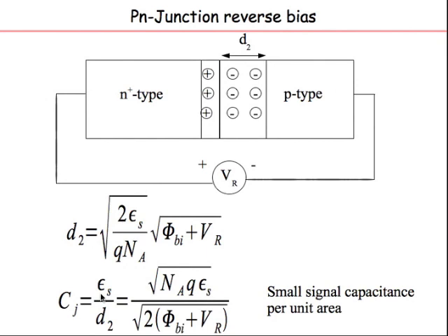In digital circuits, you have large signals. Signal swings always go from 0 to VDD. So you have to consider completely the nonlinear effects of the capacitor if you really want to correctly analyze the behavior of the circuit. That is typically very difficult to do by hand because these equations are very complex. So you have numerical techniques, numerical integration, which is done in SPICE to actually give you more accurate results of the impact of these capacitors.